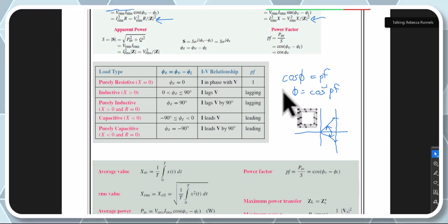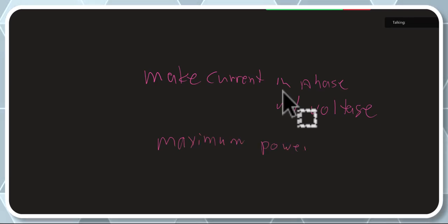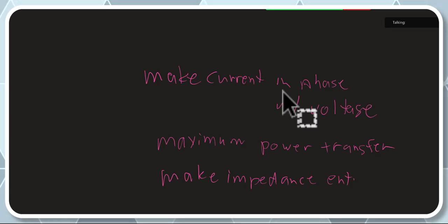So whenever you have a question that asks to make current in phase with voltage, or you're looking for maximum power transfer, or you're looking to make impedance entirely real, all of these things are saying the same thing.